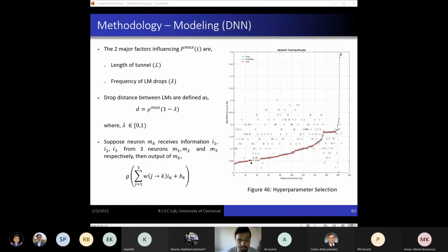We have 6 inputs. They are velocity, maximum sensing range, noise in velocity, that is the forward velocity of the vehicle, noise in the sensing range, maximum distance of travel, and overlap percentage for straight lines. We have 2 hidden layers, each with 20 nodes and 1 output layer. We selected this network after going through a rigorous hyperparameter analysis. Using 2 hidden layers with 20 nodes, we designed a network that has a decent trade-off between computational cost and performance.